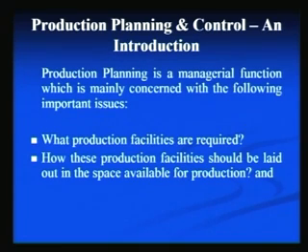So, basically here we try to lay down all the facilities on the shop floor. This is basically the physical location of the facilities on the shop floor, and we say this is an exercise we do in the plant layout. So, here we have to take into account the material flow direction, the volume of material flow and the cost of material flow while preparing the plant layout of any organization or any plant.